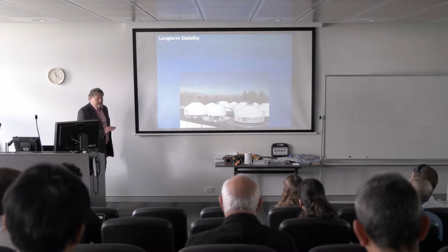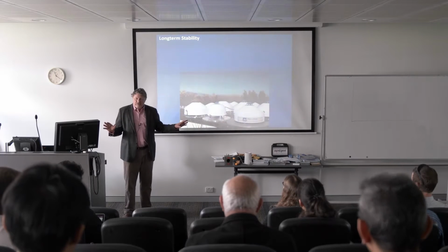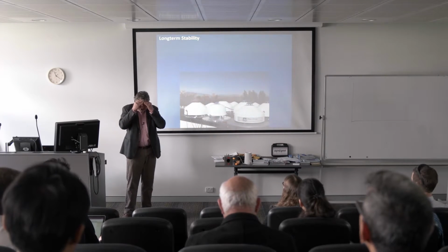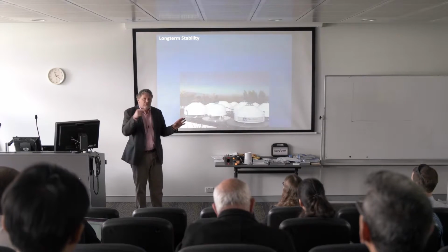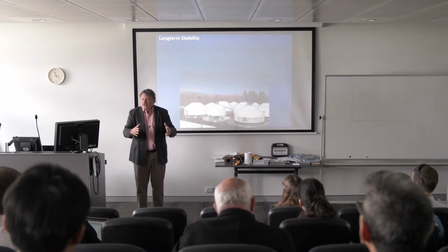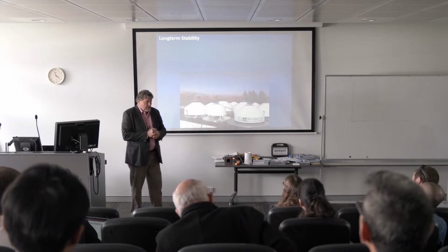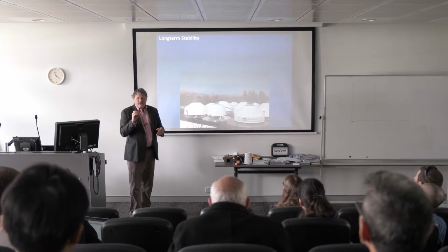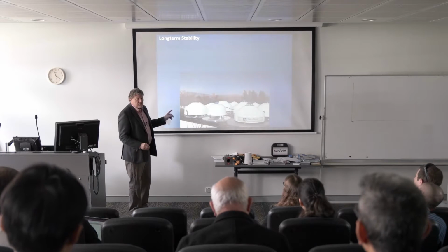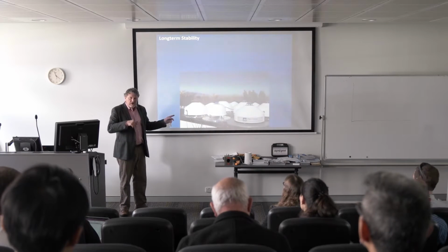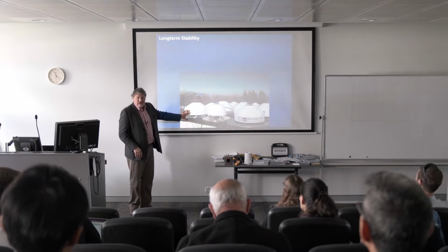Stability. This is a characteristic of all instruments. How stable are they long term? And humidity companies have said everybody can build a humidity sensor and it's accurate on day 1. Now check it 2 years later, 3 years later. All sensors drift, but companies work hard to minimize that drift. So this is some tests of silicon pyranometers for long-term drift compared to high-end black body.